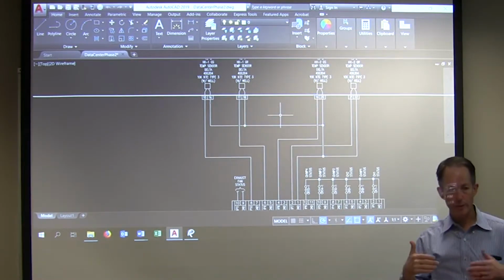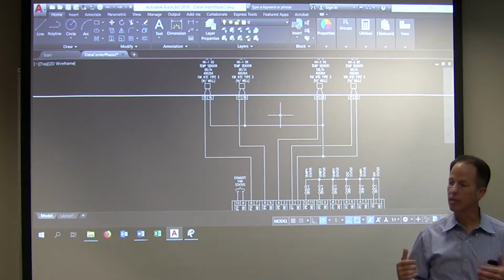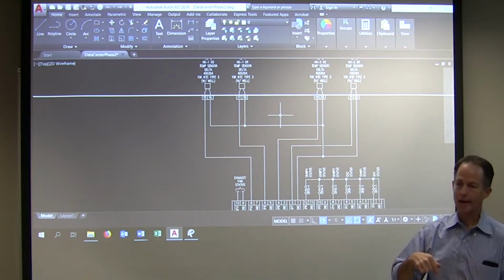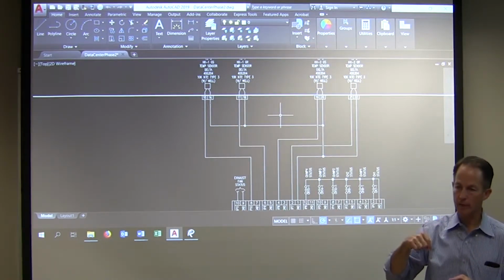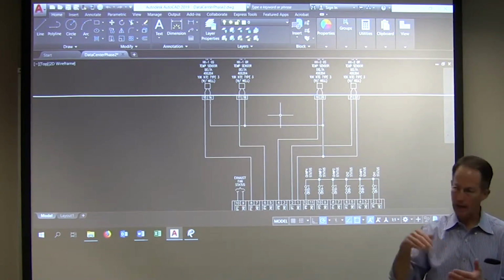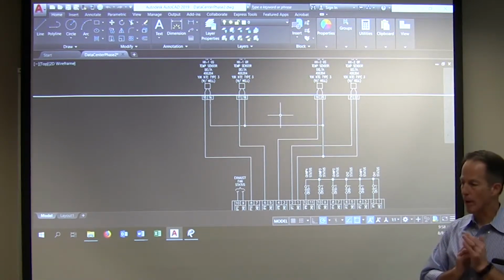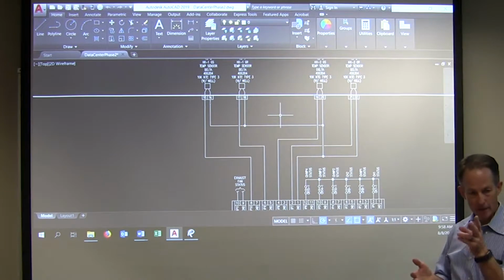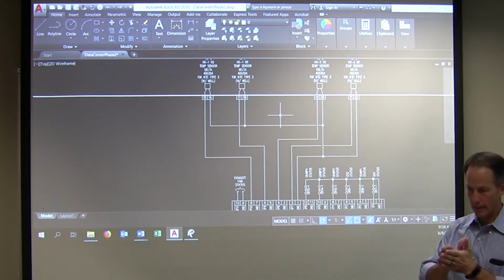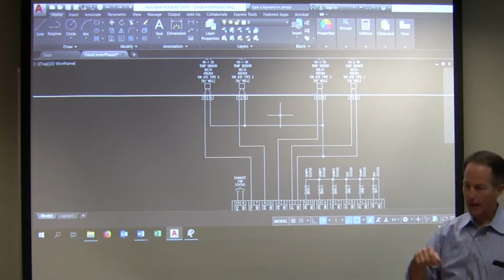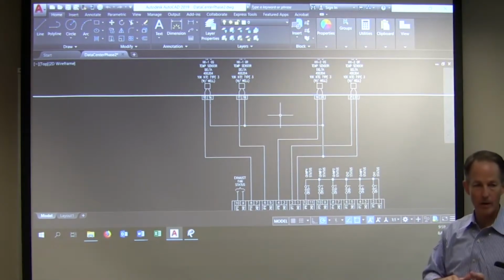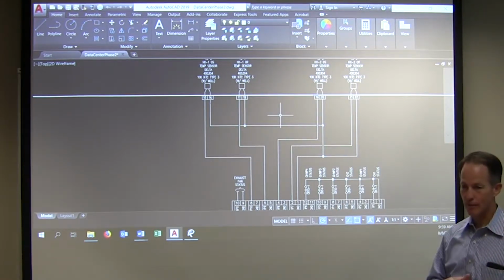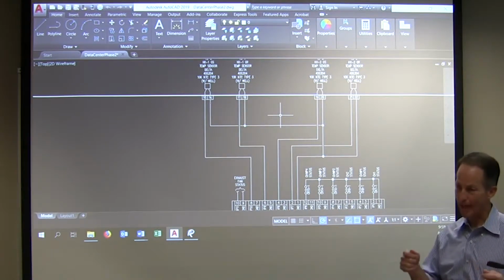The terminal strips that we typically use nowadays are spring-loaded terminals, so that as you push down a terminating screwdriver, you unload the spring, put the wire in, and then you pull the screwdriver out, and that snaps back and jams the wire via a spring into a metal contact surface inside. They're very good. I've even cut the stripped end off, so it's just a butted end, and put that in there, and that spring will push it into the metal and still make contact. I've tried to sabotage these little demo panels that we're going to work on in a few weeks, and it's tough. You almost can't make it not connect.